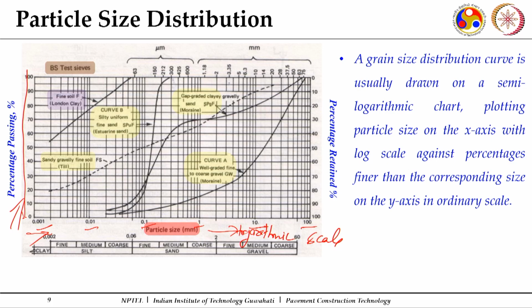Now, what important thing you can see is that I did this gradation on different samples, maybe soil or others. This gradation, or the sieve size distribution, whether it is soil or any granular material, has to be done in the same fashion. The only thing which will vary will be the sieve sizes which you will be using for granular materials and the ones you use for soils, because the particle sizes present will vary in different materials. Now, you can arrive at various pieces of information through these size distribution curves.